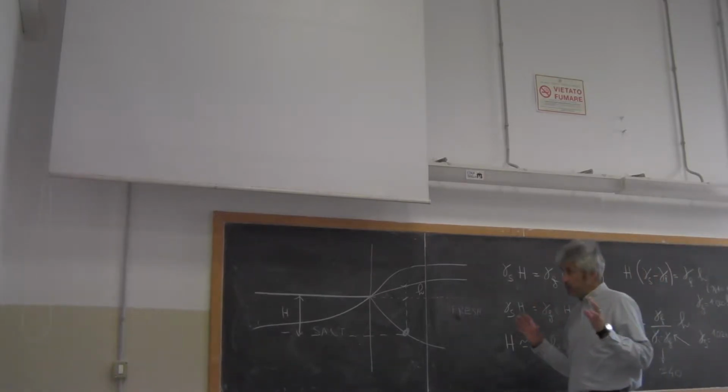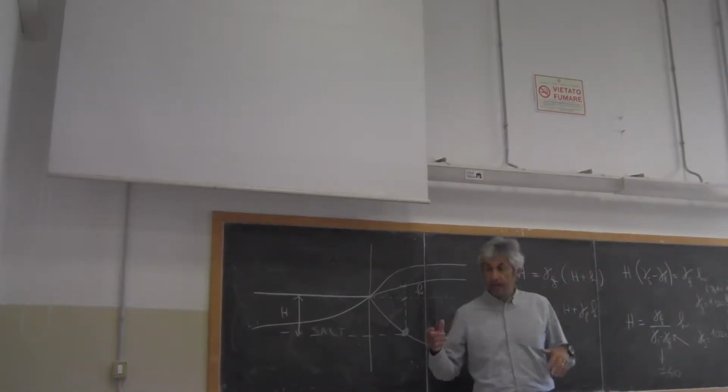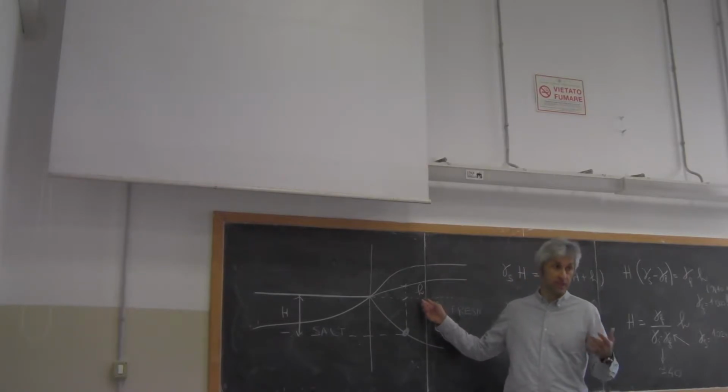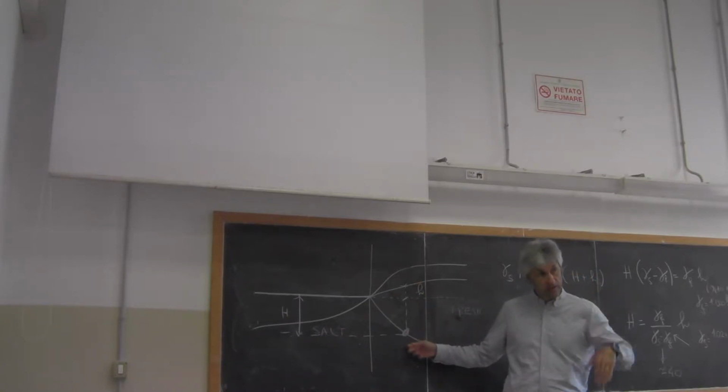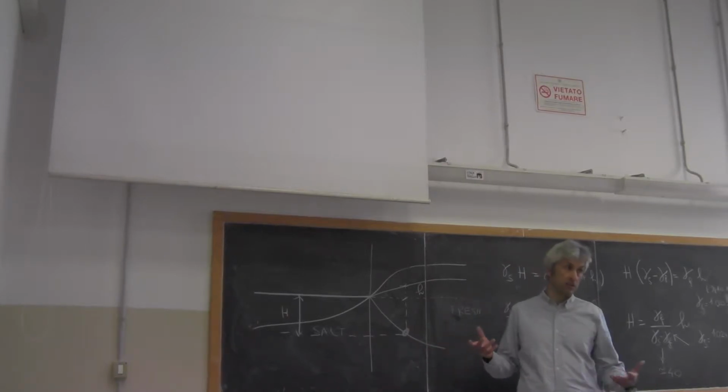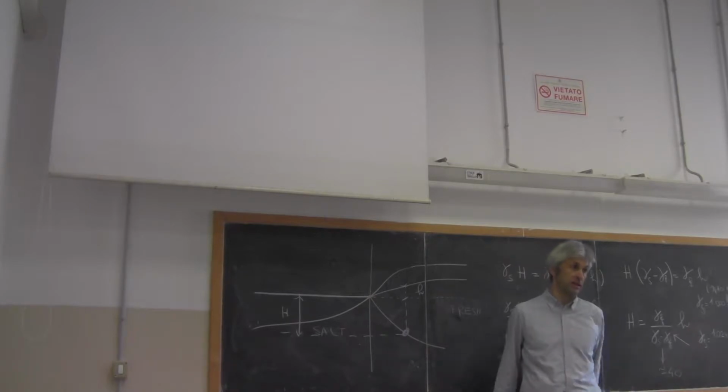Which means that if you have an excess of fresh water above sea level, which is 1 meter, then this pushes salt water in depth 40 meters, which is nice because it means that you don't need so much fresh water in order to push salt water back.